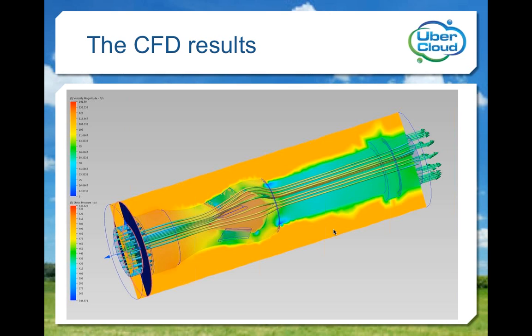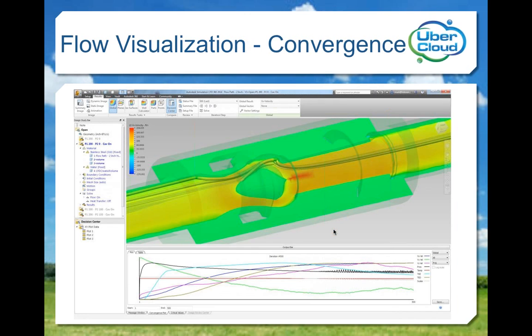As one of my Algor trainers said during a session years ago, this shows the program isn't just a random number generator. So encouraged that turbulent flow simulations with no phase change would be accurate, I eased into choke flow by setting upstream pressure to 200 psig and downstream to 0. The solution setting dialog box included an option cavitation on, so I checked it knowing these conditions would cause the fluid to vaporize.